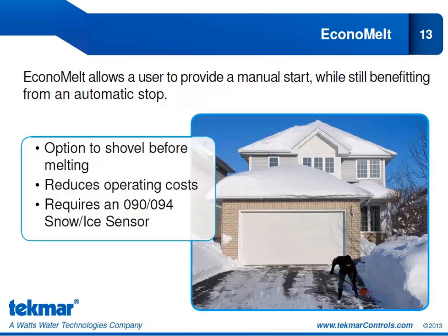So it's the economic way of melting, hence the name EconoMelt. Of course, this will reduce the operating costs for a snow melt system. And because we are using that automatic stop, it does mean you have to use the 090 or 094 snow ice sensor.